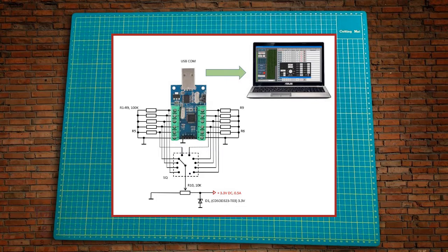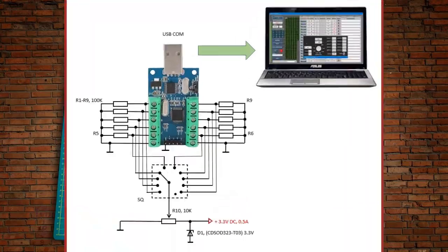We pay special attention to the protection of input channels from short circuits, surges exceeding 3.3 volts, static voltages, and polarity reversal as a result of erroneous connections. The topic of protecting input and output control stages is the subject of separate publications, which we will not consider here. To begin with, it will be enough to get acquainted with this scheme, which is suitable in most situations.